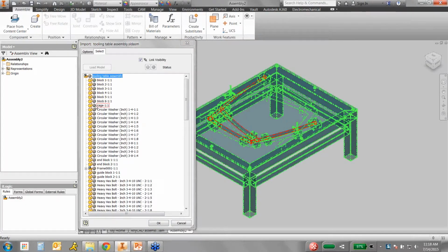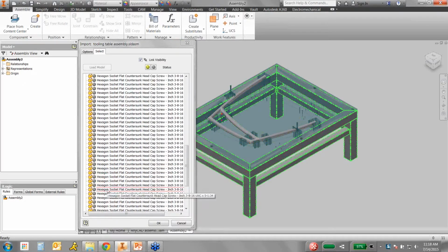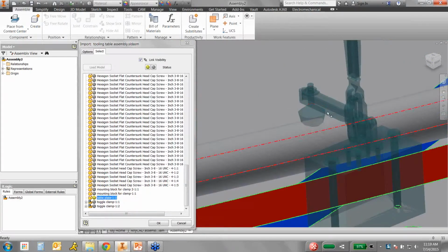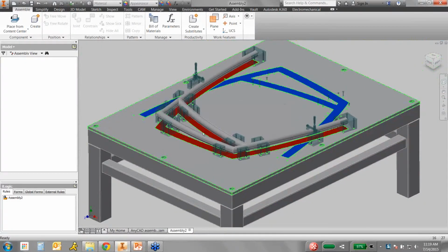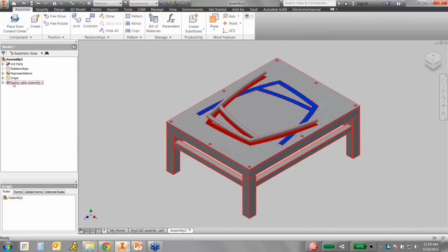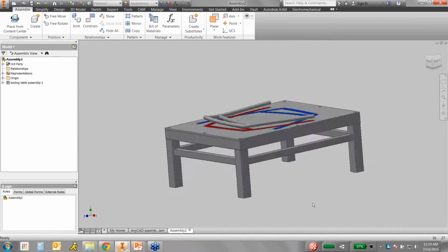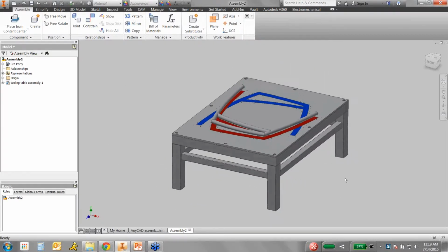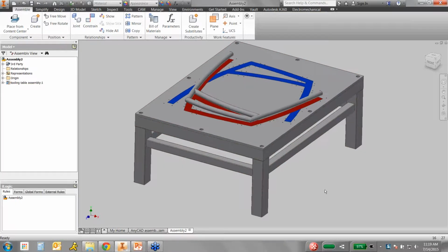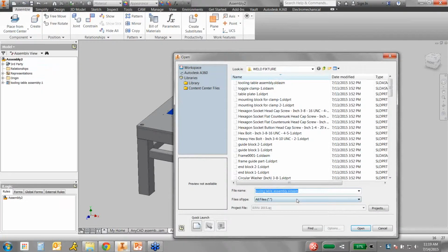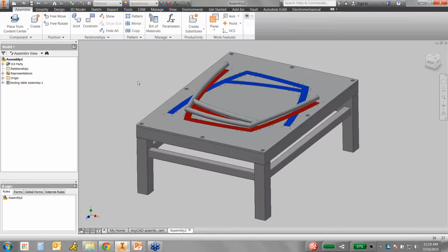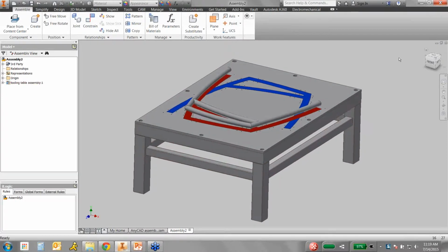So I'm going to go ahead and only enable the cage, the frame, and the plate. I don't need all these toggle clamps and blocks, so I don't need to load those into the Inventor assembly. Again, we have an AnyCAD assembly directly inside of Inventor now that we can work with. Maybe even build some of those other detailed pieces on our own. So place imported CAD files also in the open dialog. If you just go directly to another format, we can now load them instead of importing them as we used to.